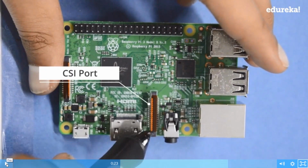This is a CSI port. So it supports a camera also. The CSI port is a standard port where you can plug in a camera. So you'll get cameras which support the CSI port, and you can straight away connect your camera here using a cable. So your camera is straight away connectable to a Raspberry Pi.